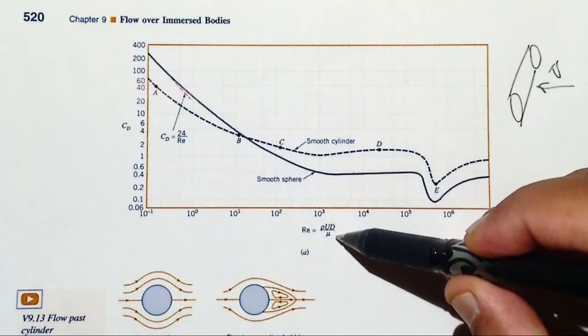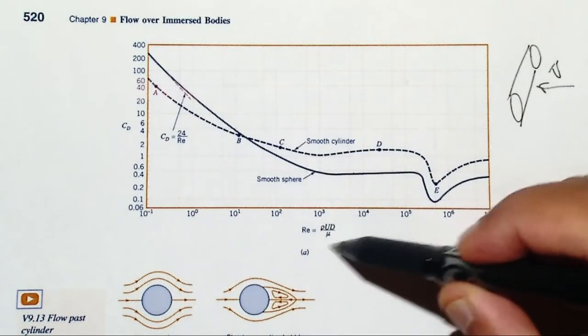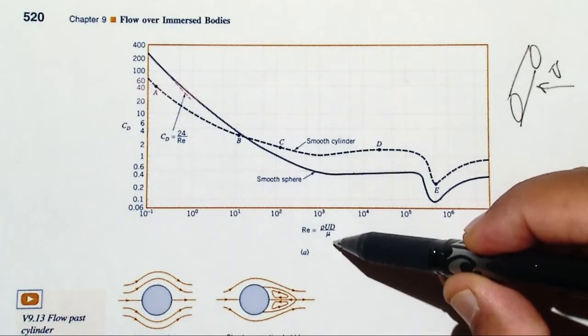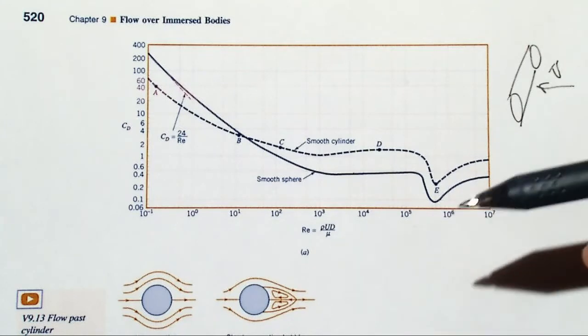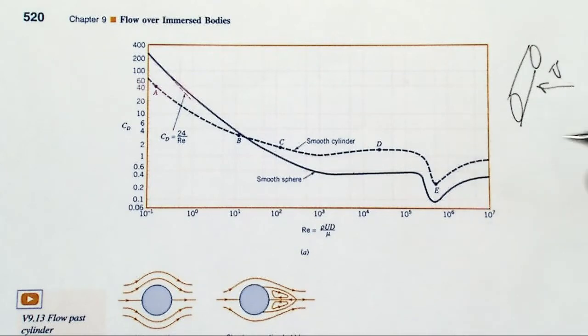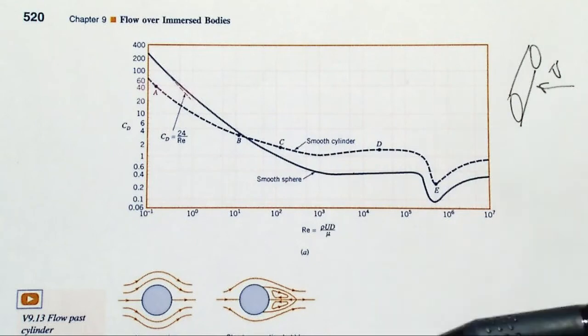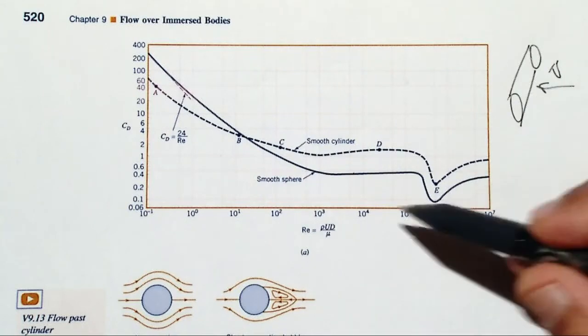You bring the scale and the velocity of the flow inside of that. Then you don't need to worry about the scale, because the Reynolds number has the information for the scale of the object, because of the characteristic length and also the velocity of the flow, and also rho and mu, which are the fluid characteristics, right?